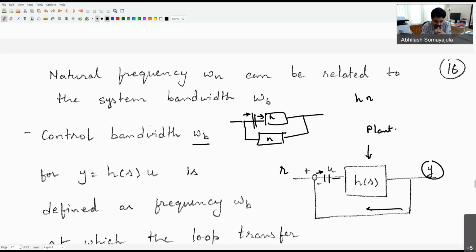You remember, if you have ever observed in our online meetings, sometimes we get a feedback in our system, right? So I speak something, but then it gets amplified and keeps getting amplified over and over and over again. So what is happening there? My speaker is giving out the output, which is being picked up by my microphone, and then it's getting amplified again and again. Okay, so this same exact process is happening there. So when your loop is not stable enough, if the loop's transfer function is more than 1, it's trying to amplify your signals in a certain range of frequencies.